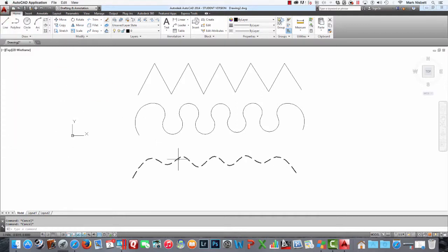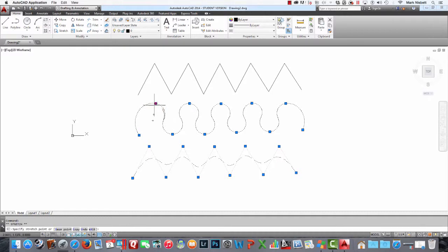Also notice that you get the frame on the spline curve, and on the fit curve you don't. You get the grips on here to actually change the vertex point like that. It's going to hold the first one, it's going to hold the second one, but this one here will change. In here you're changing the actual frame itself. You can kind of see how that works. It's using the frame itself, because this is what we call the Bezier curve.